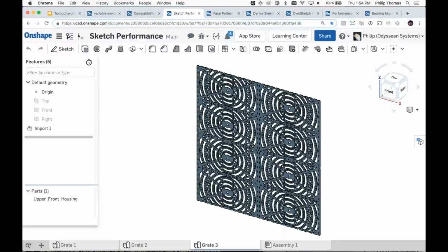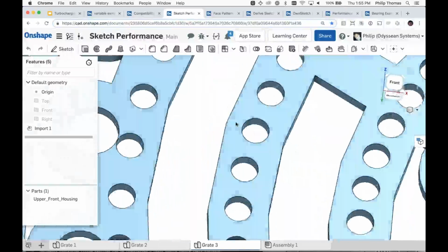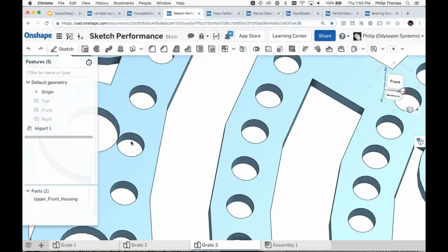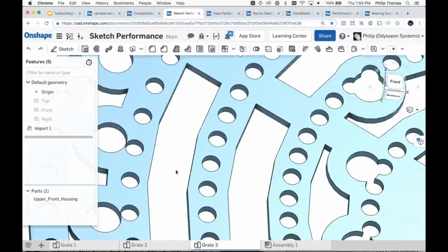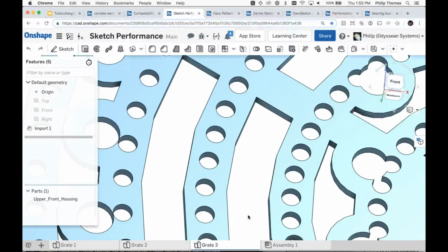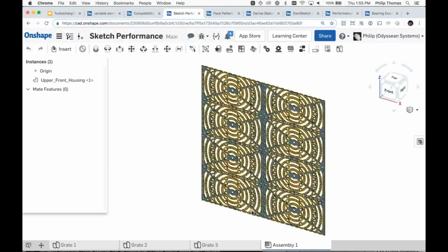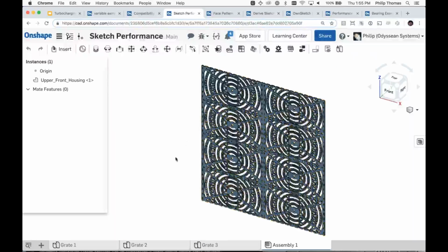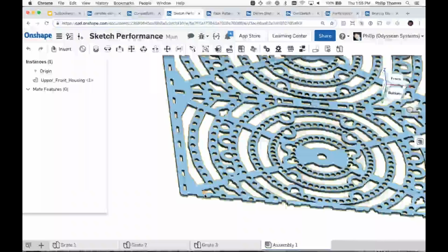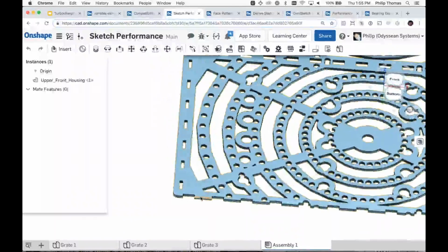So usually it's 2 or 3 more. Of course, my computer could have been doing something at that particular moment in time, but you can clearly see that there are smoother edges now. And if I went all the way up to fine resolution, you would see that it takes about 30 revs. So the fewer triangles you push around, the better. If you have a small fiddly part, you need high resolution, feel free to crank it up. If you don't, the lower, the faster it is.